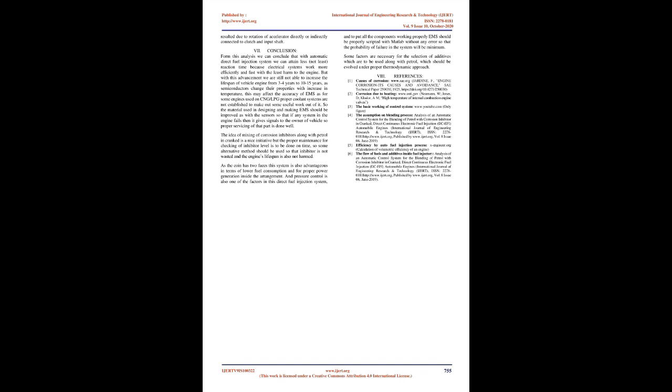With the addition of additives: additives are used in an engine for preventing corrosion effect, creep, and freezing effect. As for lubricating, they are used with the life support system. Some assumptions related to this topic. 1. The calorific value of additives must be near to that of fuel. 2. The additives must be completely combustible in presence of high pressure. 3. No third product should be formed after combustion of fuels which can cause harm to the environment. 4. Additives should not change any property of fuel, which may affect the performance of the engine.